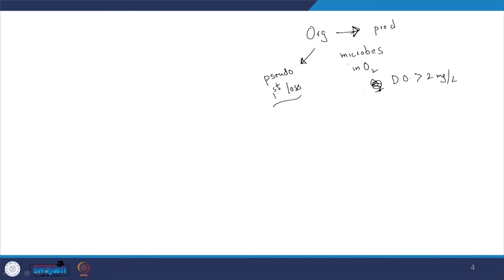Let us say k is the rate constant, and to use the usual nomenclature, L is the concentration of the organic content. So, initially I have L naught, this is not L out. In my sample, I want to be able to estimate it. This is my sample, a closed system, meaning it is a batch reactor. I want to estimate or predict the behavior of this organics, and please note that I am applying the mass balance on this organic content, and this is a batch reactor.